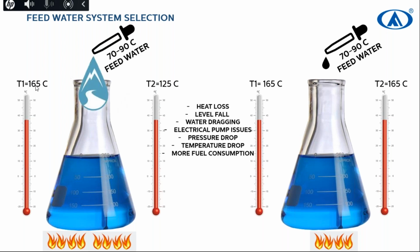With on-off feed water, the temperature can drop because when the system reaches the low level, it fills with a huge quantity of water. For example, 300 liters suddenly get into the boiler, which reduces the temperature and also causes pressure drops with on-off control. You will also need more heat to raise the temperature up again, in this case from 125 to 165.